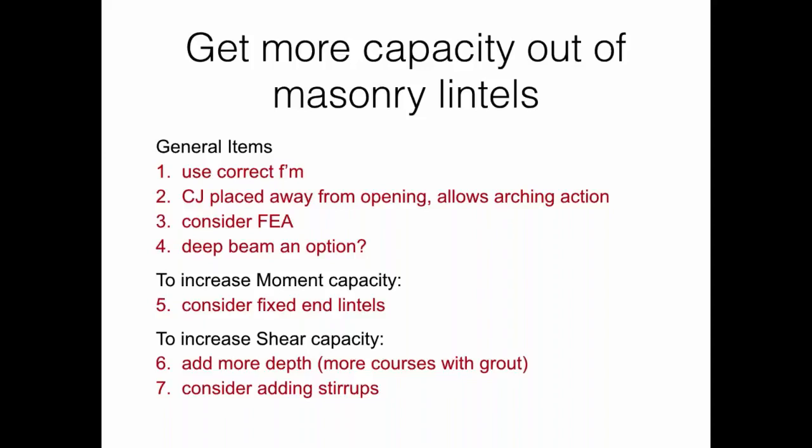And then just a couple suggestions there. If we want to increase the moment capacity, we just add top and bottom reinforcement. Add shear capacity, just add more depth, or you add stirrups.